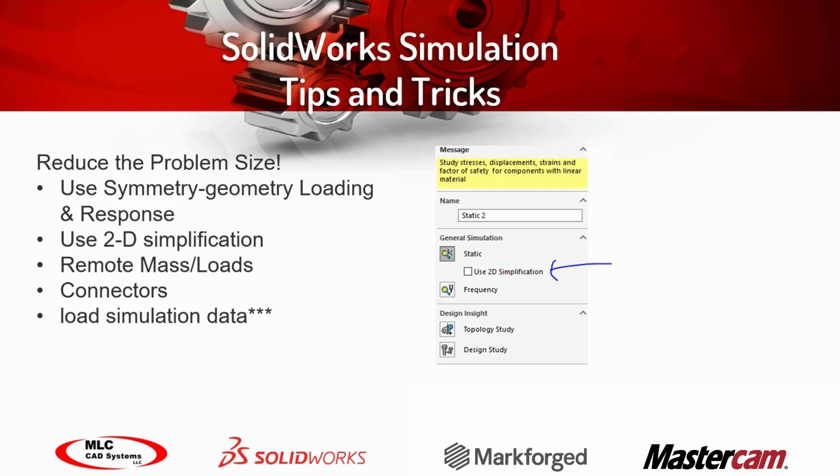Those of you that have Simulation Professional get another added benefit: if you have toolbox components, you have an option to automatically convert those to simulation connectors without having to go and manually define those one by one. You can also load simulation data if you're using 2018 and above to bring in the mesh at the component level to an assembly so you don't have to remesh again at the assembly level. You can also bring in things like loads and fixtures from that component level as well.